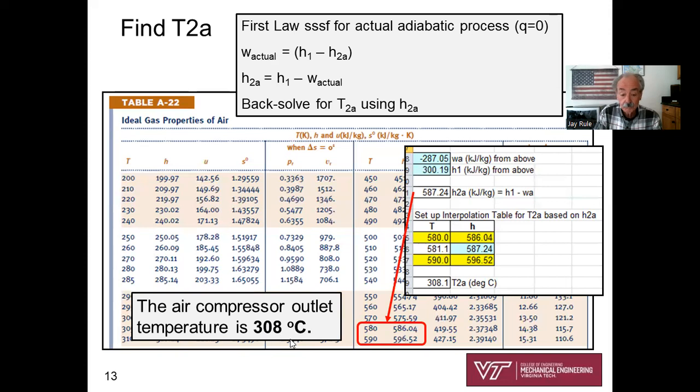So we want to be able to touch the pipe that's conveying the compressed air. So we've got to have compressed air that's maybe 40 degrees C or 50 degrees C would be the absolute hottest we could sustain. So we'll need to add a heat exchanger that's called an after cooler to this for a true industrial installation of an air compressor.